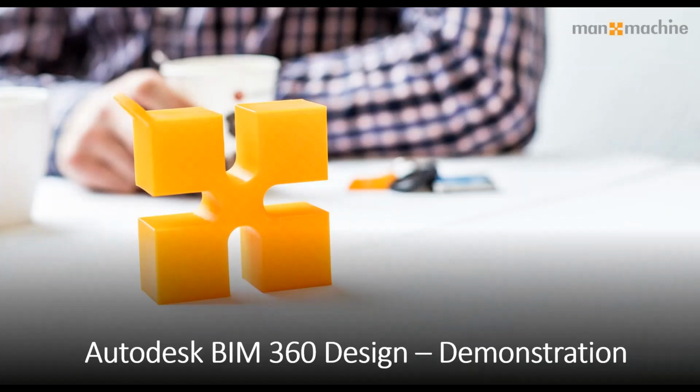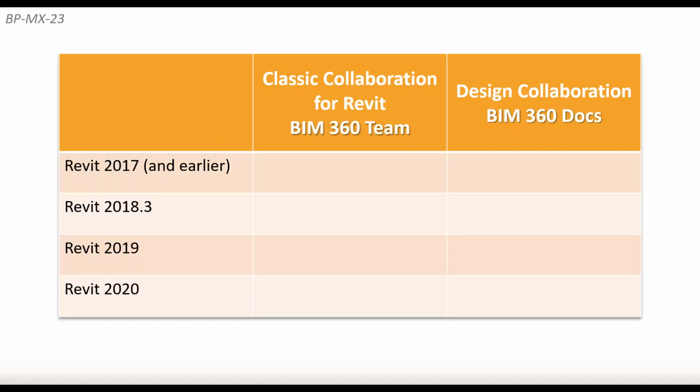A couple of things I want to just point out before I move on a little bit is, if you're using BIM 360 and you're using Revit, for example, 2017, 18, 19, and so forth, you need to consider a few things. So if you're using 2017 or earlier, you can use the classic BIM 360 Team. You can still use it with 2018 version 3, but that's when it switches over to Docs and Design Collaboration for the later versions itself. So that's something to bear in mind for you guys.